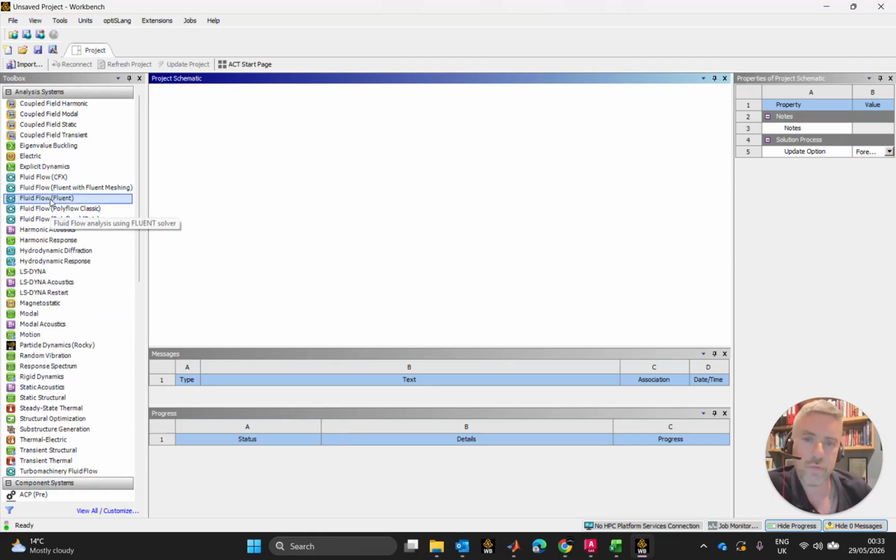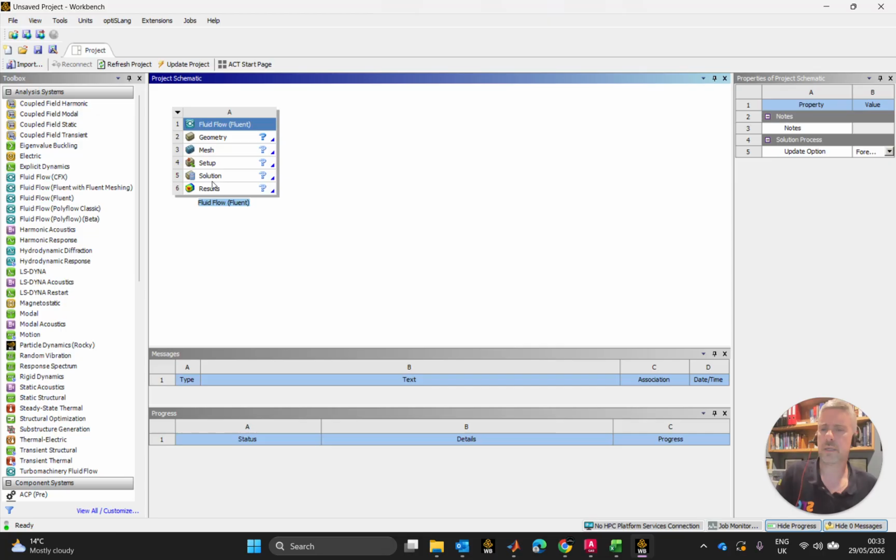But for the workflow that I'm following, where I'm using parameters really to drive the geometry, the analysis system seems to lend itself somewhat better. So with that said, I'm going to bring in an analysis system for Fluent, Fluent being my chosen solver in this. Now, the name of this system I'm going to call E423. So I'm going to use an Eppler 423-ME for a main element.